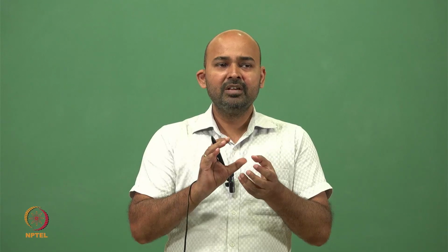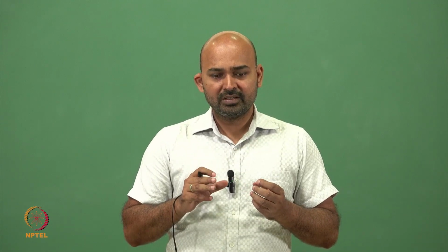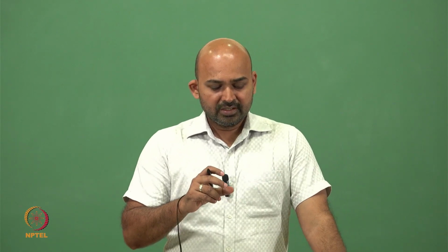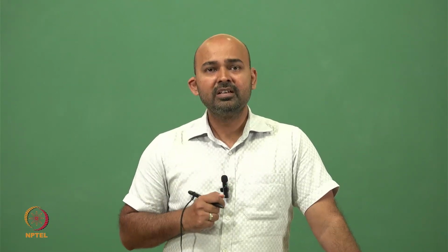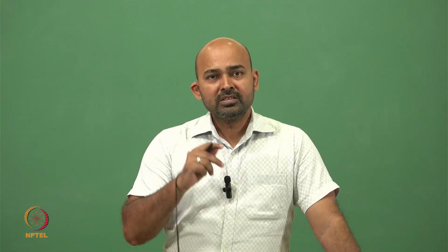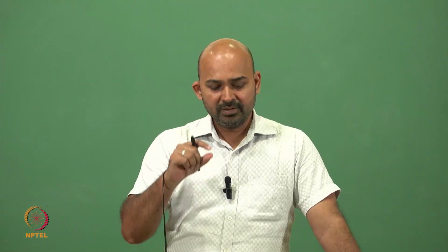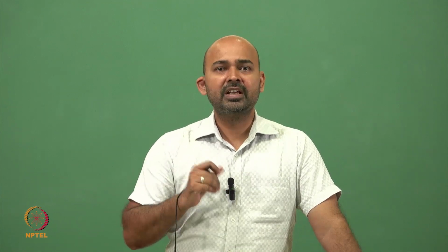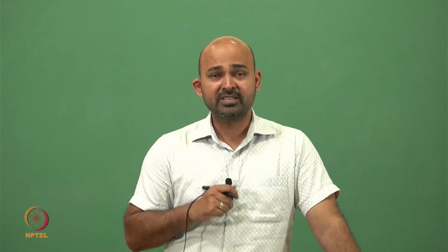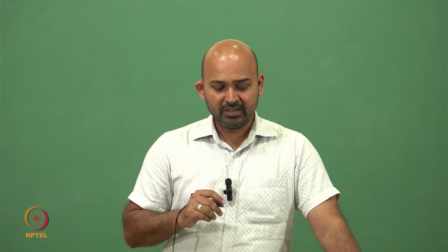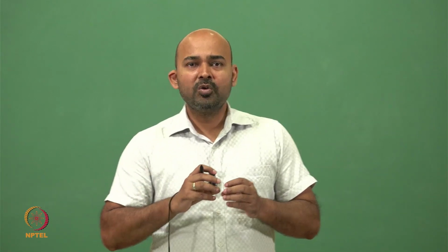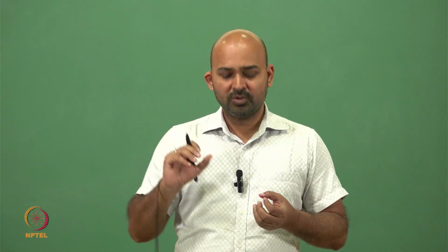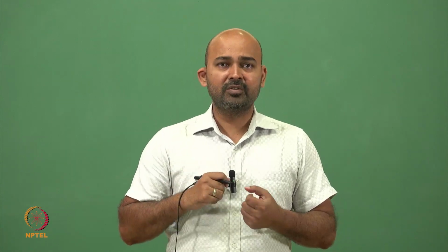So we can have some sort of bridge completion. For example, the Wheatstone bridge we use for resistive measurement. This kind of bridge completion is provided by the signal conditioning unit. Now this signal, which is still a very small signal, 0 to 10 millivolt, is applied to an amplifier, which can be an op-amp based amplifier or a BJT based amplifier. This must be a linear amplifier. This amplifier is now going to amplify the data from a few millivolts to the volt range, 0 to 3 volt or 5 volt as per our requirement.